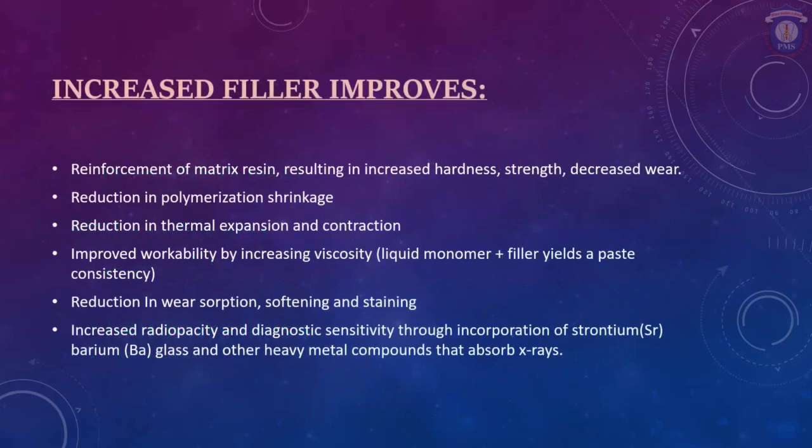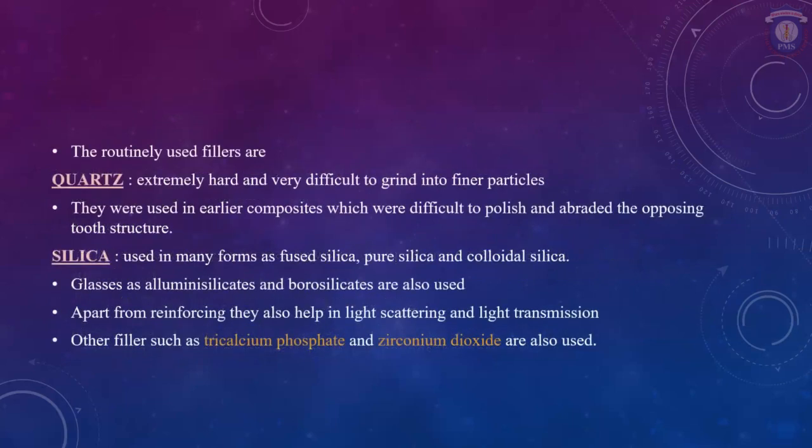An increase in filler improves the reinforcement of the matrix resin, resulting in increased hardness, strength, and decreased wear, a reduction in polymerization shrinkage, reduction in thermal expansion and contraction, and also improved workability by increasing viscosity, reduction in water absorption, softening and staining, and increased radiopacity and diagnostic sensitivity through incorporation of strontium, barium glass, and other heavy metal compounds that absorb X-rays.